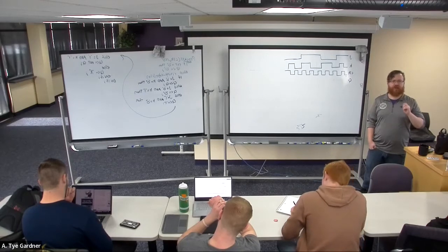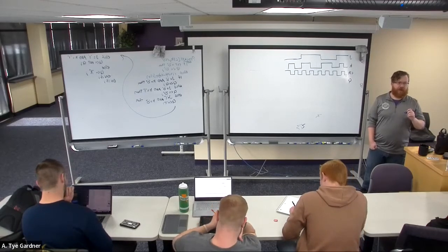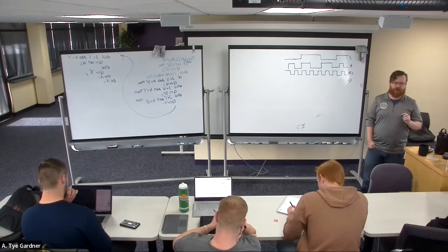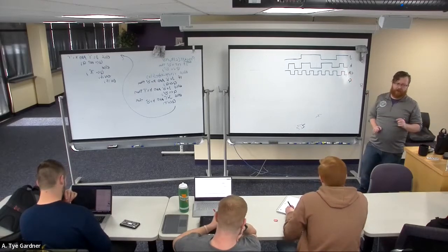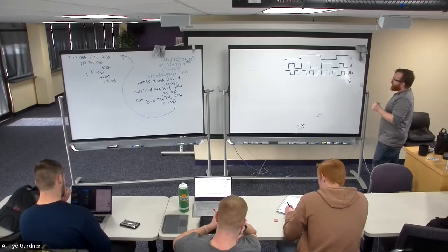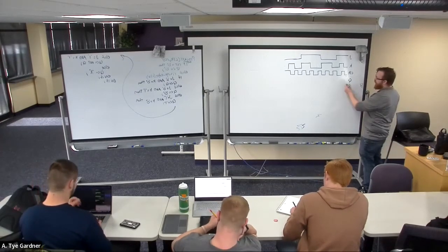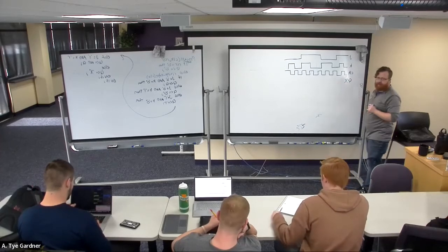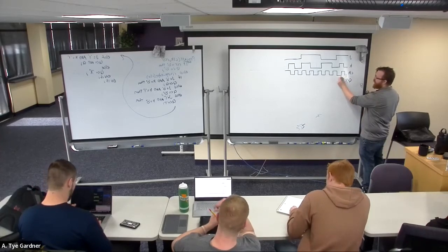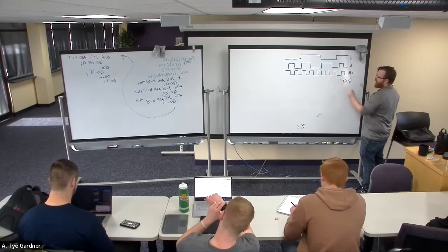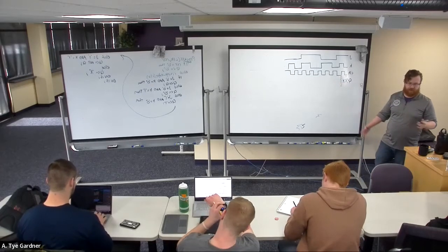Let's say the question is, we want to do the timing of a falling edge triggered JK flip-flop with these input waveforms. So the first thing that we do is, if I don't tell you that Q is something to start with, then the answer is, I don't know. In fact, I can't possibly know what Q is until the first falling edge.